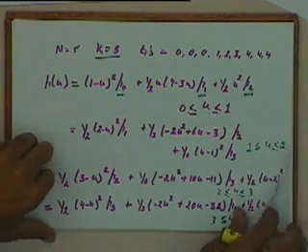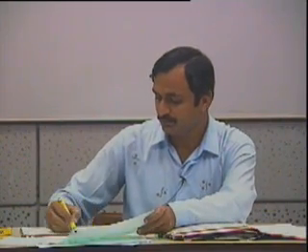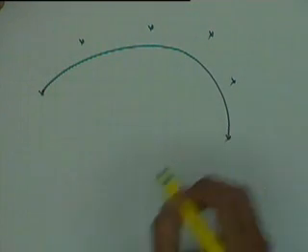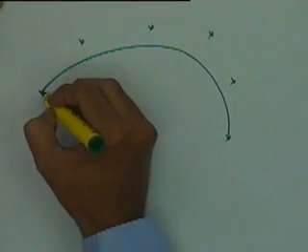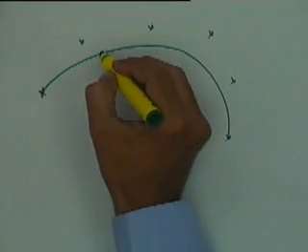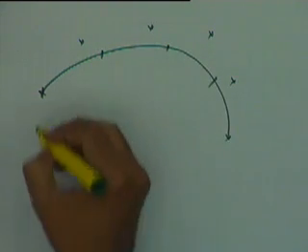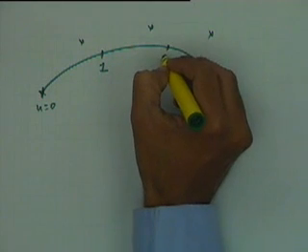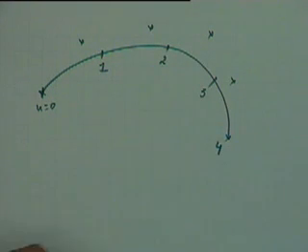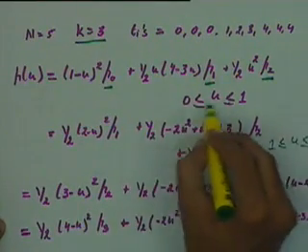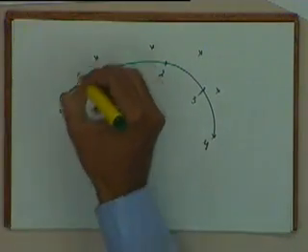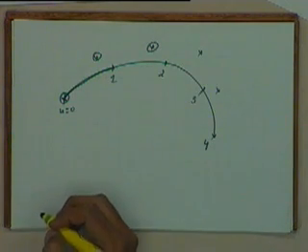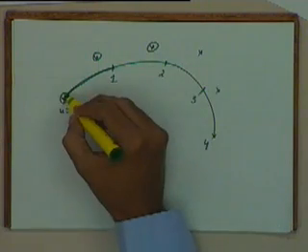What that means is, if we have 6 points like this, I have a curve which is defined like this. My knots will be defined at 0, 1, 2, 3 and 4. So this is u equal to 0, 1, 2, 3 and 4. For this part of the curve between 0 and 1, P0, P1 and P2 are effective. So for this part of the curve, these 3 points are effective. If I change this point, this part of the curve will not get modified.